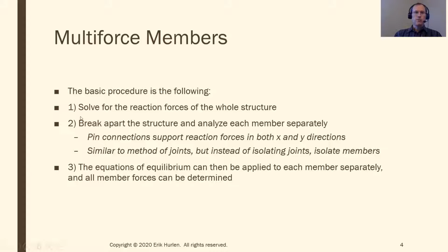The real meat and bones of this is to take my entire structure and break it apart and analyze each member separately. Similar to what we saw for method of joints, where I only looked at one individual joint and ignored everything else and only did statics analysis on that one joint. Similar thing here, but instead of looking at the joint, I look at each individual member. So I take that one member, pull it off of the entire structure and analyze that one member